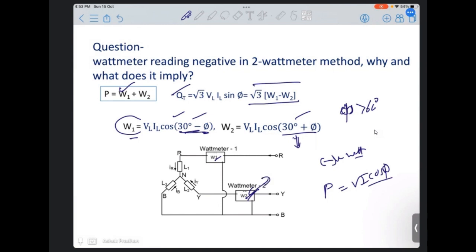Yes, the wattmeter reads negative. But what is a wattmeter? In the digital domain, the wattmeter is nothing but a voltage phasor, computes the current phasor, finds the angle between them, just like a relay, and then makes the corresponding calculation VI cos phi. So voltage is calculated, current is calculated, VI cos phi is calculated, with phi the angle between voltage and current, whatever line voltage and whatever angle comes between them. Today the digital wattmeter is nothing but a calculator. Whatever V, I and phi happen to be, accordingly the value comes. Just like a calculator, whatever inputs you give, the calculated value comes.